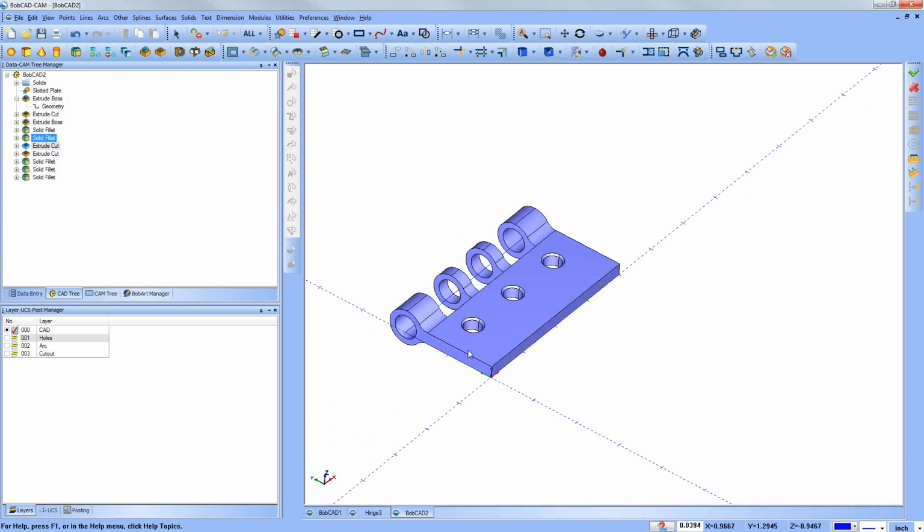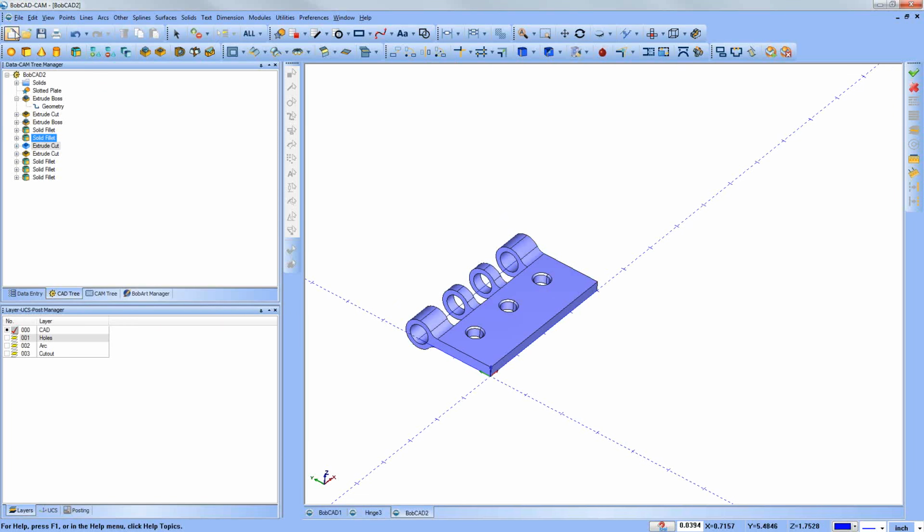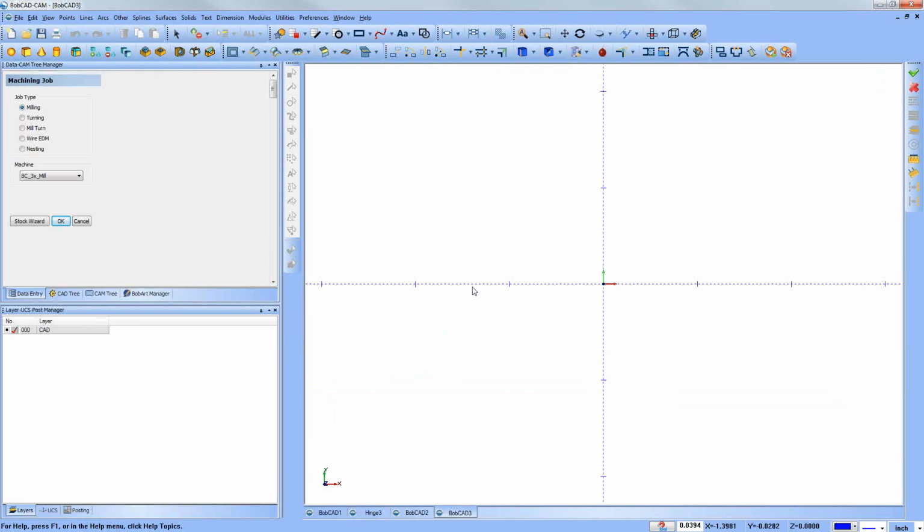I created this by extruding the rectangle here, then extruding this cylindrical surface, this cylinder here, and then I put some fillets on it. But really, what we need is just this profile, this shape in 2D, and then we can make an extrusion. So, looking at maybe a new window just for a moment.